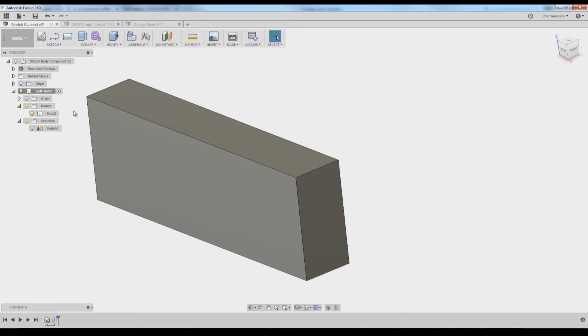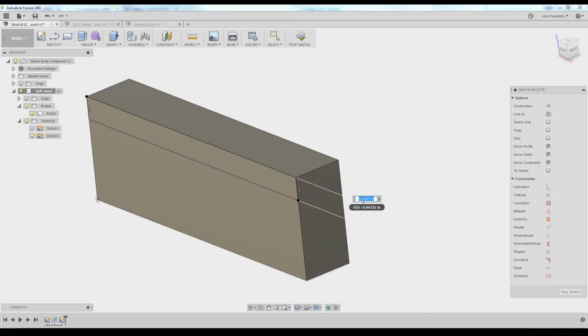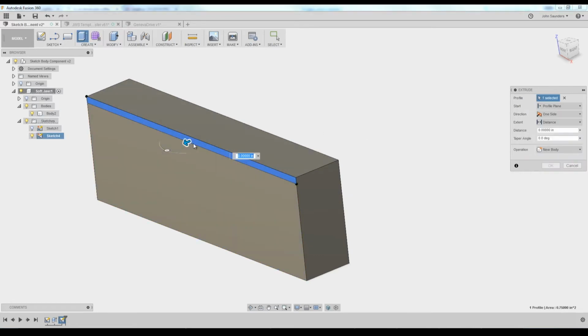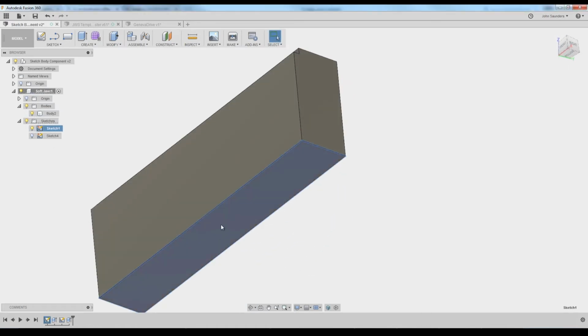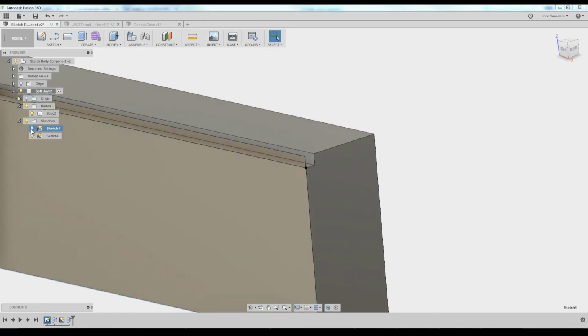It is really important that when you create sketches, you put those sketches in the component. For example, let's say I want to add a shelf to this Softjaw. Notice I'm active on this Softjaw component. R for rectangle, and I'll sketch a rectangle, dimension it, 0.125, E for extrude, and we'll extrude that in negative 0.125. So you can now see my Softjaw component still only has one body, but that body has the sketch of the floor, where I extruded up the major part of the Softjaw, as well as the sketch up here that I used to create the indentation.